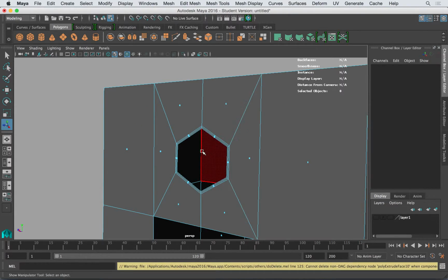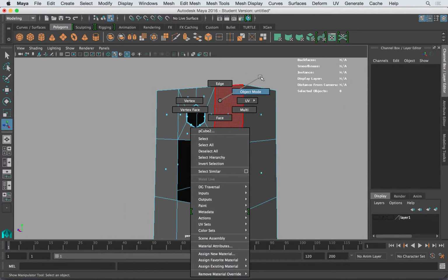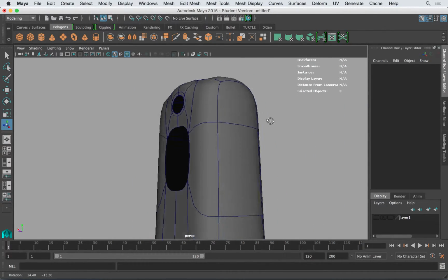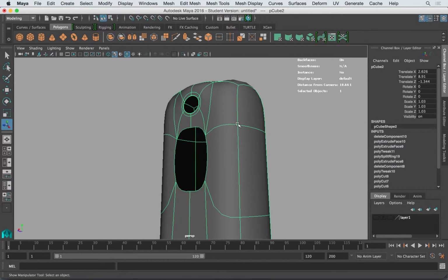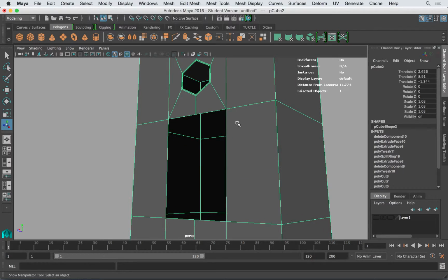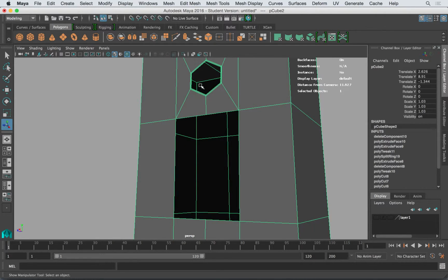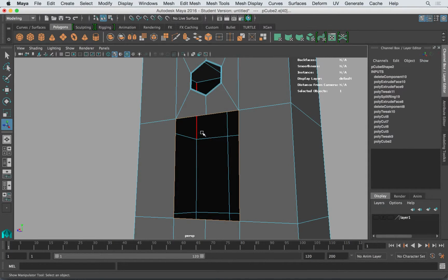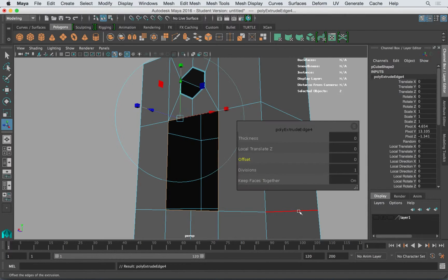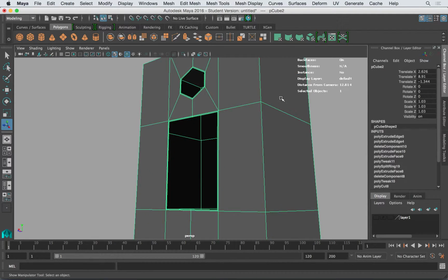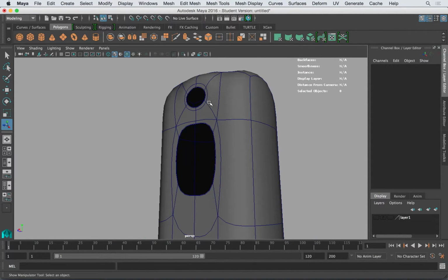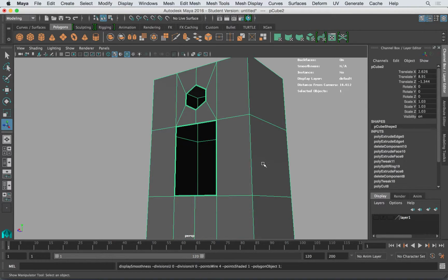So I'm going to delete the other parts. So I have 1 and 2. If I press 3 right now, this looks like a very smooth object. We don't want that. I should have done the same for here, but it's okay. I should have done the same thing for that hole here, so I can do it right now. I can select this edge and do an extrusion with a little bit of an offset, 0.02, and do another one, 0.02. Okay, let's see how that works. So there's a little bit of a sharpness here. Now everything else is really low.